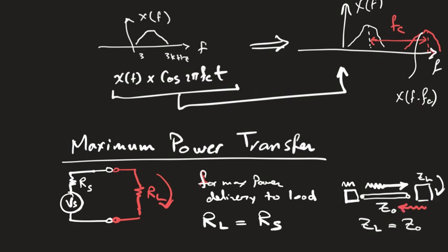Okay. What's bad about reflected waves? Two things. Number one, efficiency-wise, there is part of the power that's not being used by your load, right? That's a waste of power, or a waste of energy. The second thing is those reflected ones, they get eventually consumed as heat in the source. So your source will start heating up, building up heat. And in RF system design, this will mean that after a few minutes, sometimes after a few seconds, your whole system is going to stop working.